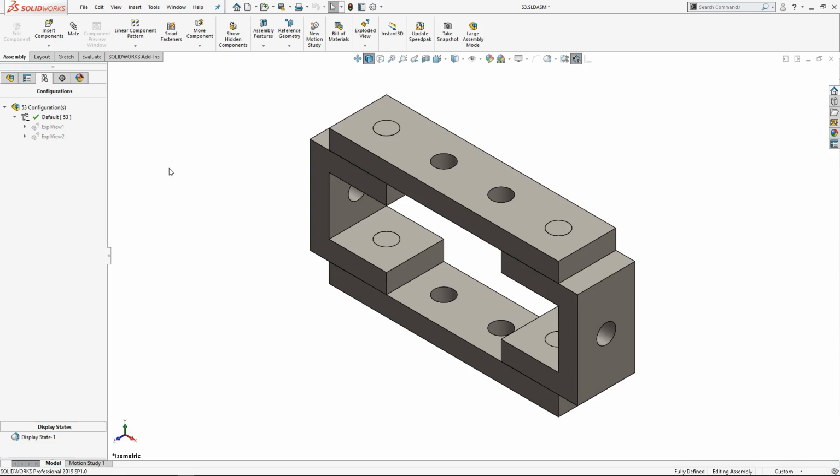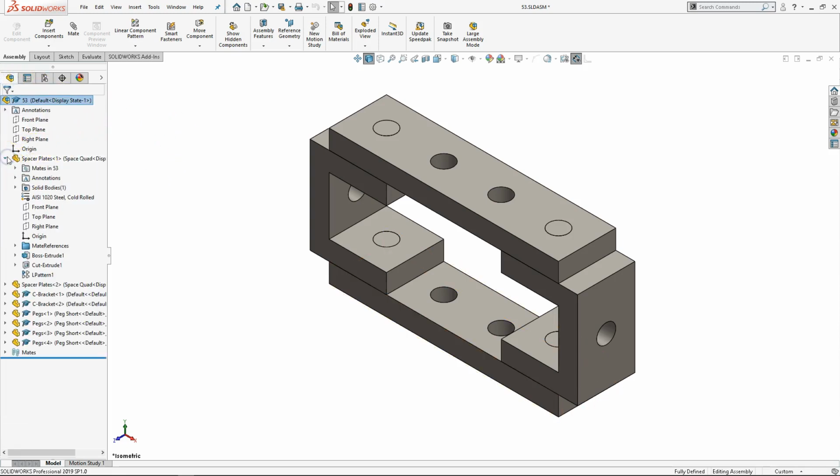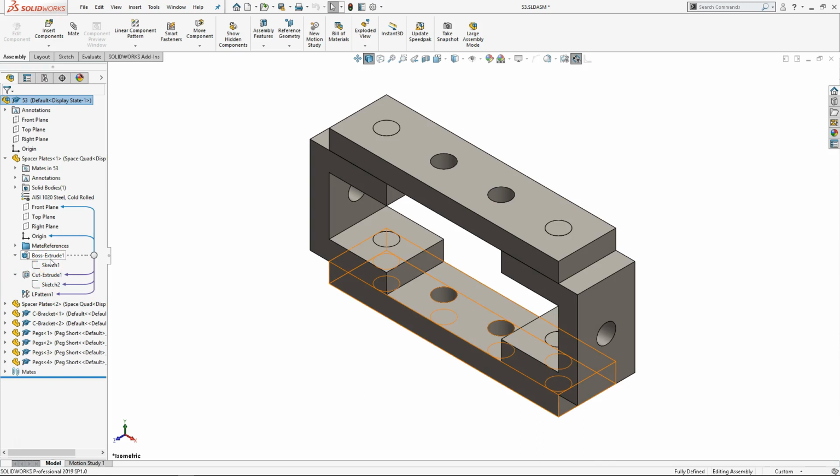But as you go through building, we're looking for some specifics, at least from a modeling standpoint, and it doesn't matter if it's Fusion, Inventor, SolidWorks, NX. They're all going to have very similar rules in that you need a fully defined sketch. There are no happy accidents. Right? So if I expand out and look at a part, and I look at any of these features, if I see minus signs in front of these, that means that part can move in unexpected ways. It can grow, it can shrink, it can have unexpected consequences.